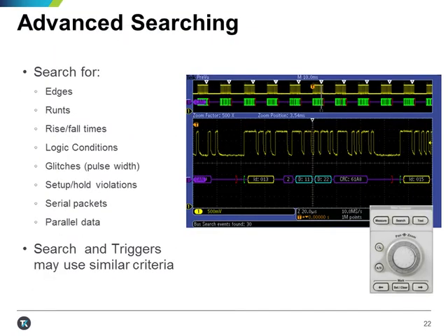With today's long record lengths, search tools have become almost as important as trigger tools. Capturing an anomaly is only a good first step. Once you catch it, you still have to find it in the scope's memory. You'll want to check out this capability, especially if you're leaning towards an oscilloscope with a record length of millions of samples. Many Tektronix oscilloscopes include a neat facility called Wave Inspector.